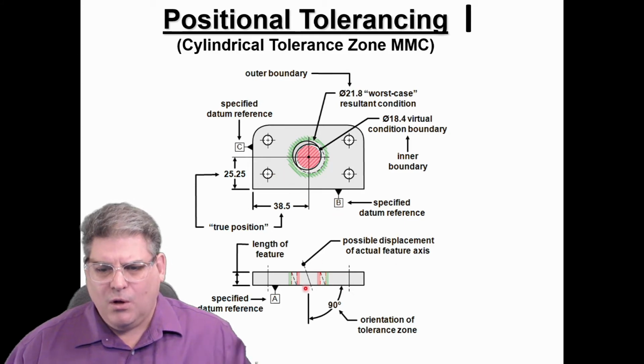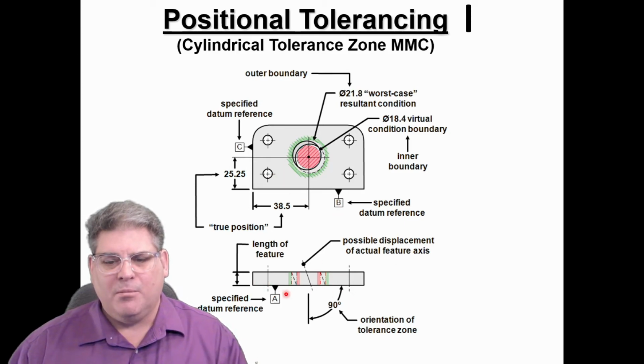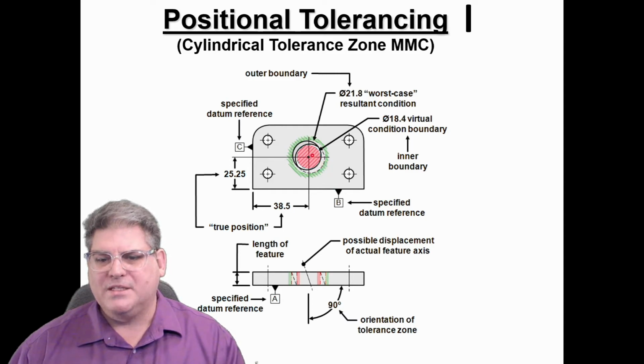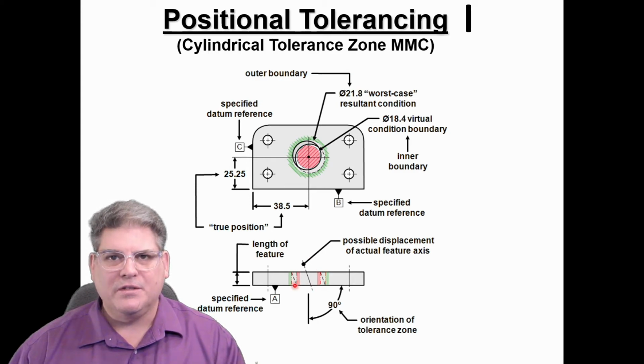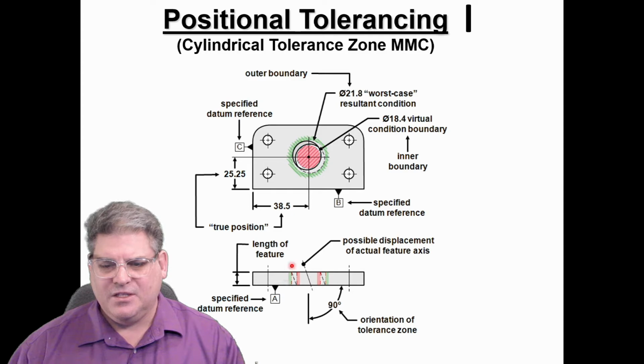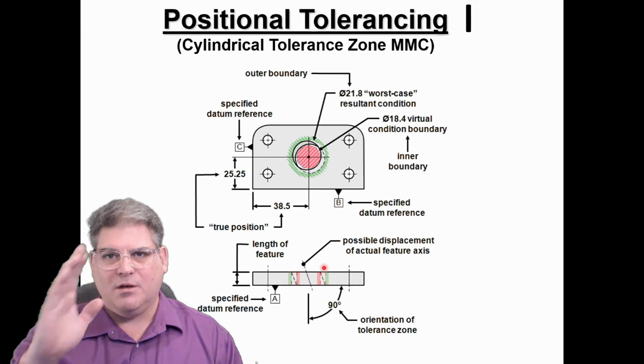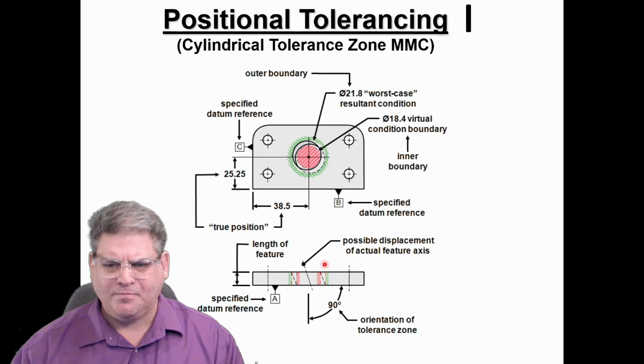Okay, so they've got datum A being their main feature, datum B again being the surface, and datum C being this line. And when they put in the true position, okay, then they're looking for the worst case scenario of that hole being out of round, so that if you drop in, let's argue it is a switch, that it's still going to be able to sit square. You don't want your switch sitting on some angle. All right.